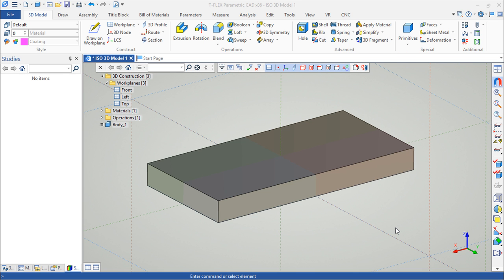Anisotropic materials differ from isotropic materials because their physical properties, where we can include elasticity, Poisson ratios, thermal conductivity, and others, have different values depending on the orientation of the body in space.